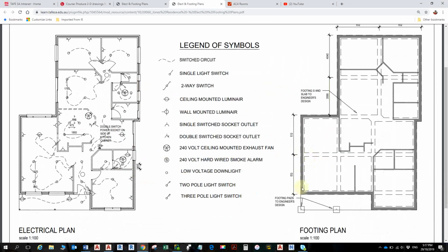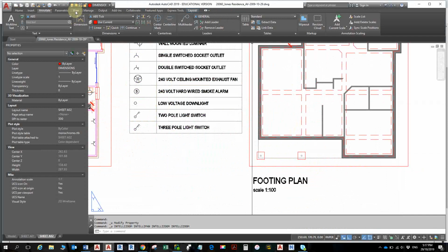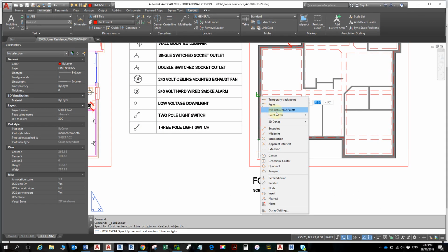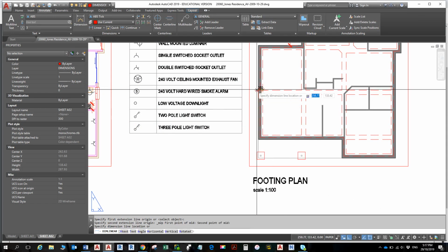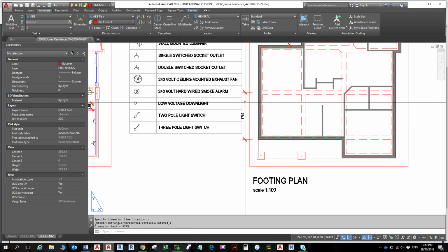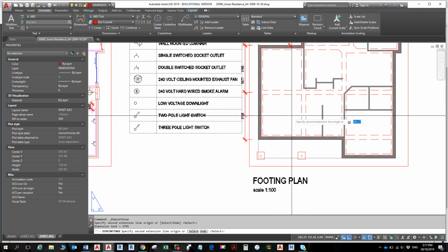And here, the same. We'll put that dimension on. We're going to go dimension, annotate, this one here, and there. Shift right click, meet between 2 points, there to there. Drop that about there somewhere, and continue to the other corner there.